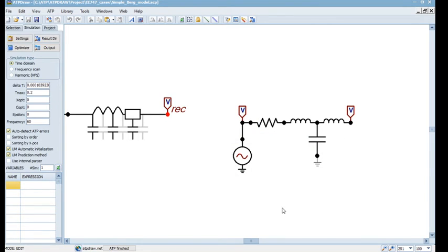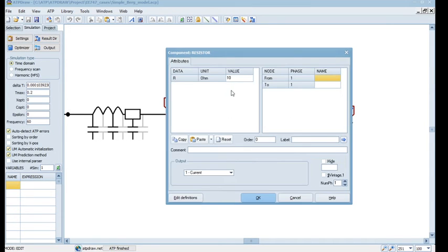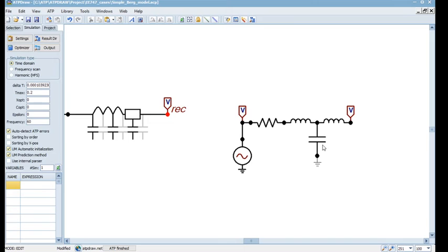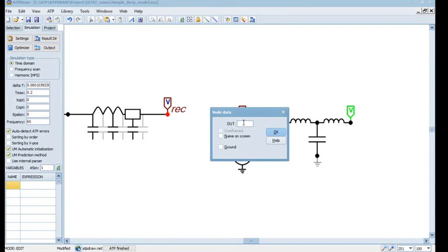For example, if you want to see this, how to demarcate this voltage and this voltage, you already know that. See, everything is the same, fine. 10 ohms, and the voltage is also the same since we copied it, so no need to show you the setting, but for the sake of completeness. Logically, even if you place the voltmeter here instead of there, it should not hamper, isn't it? But let's keep things as they are. I'll call this receiving end underscore lumped, so REC underscore L.